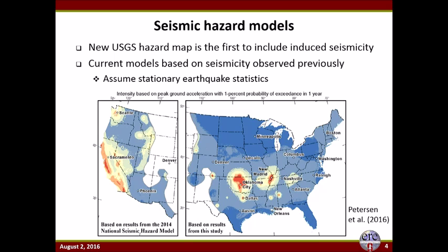And furthermore, it assumes stationarity. That is, the earthquake statistics that drive the model are assumed to remain constant throughout the period of the forecast. Now, because induced seismicity is related directly to the way that we're injecting fluid into the subsurface, these models could be improved by incorporating some operational data.